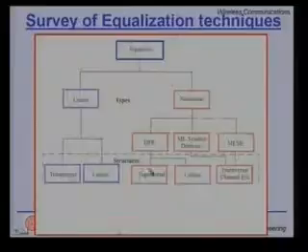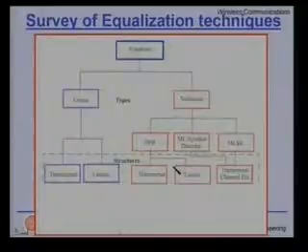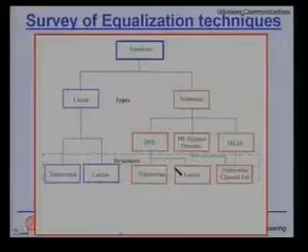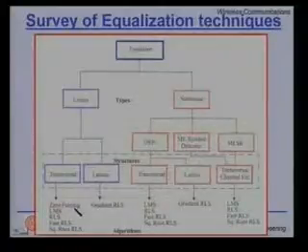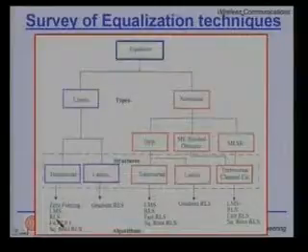Now, for each of these structures, you have the flexibility to use various kinds of algorithms to quickly update the weights. Most of them are recursive algorithms. You could either use the zero forcing or LMS, least mean square, or RLS, recursive least square, or the variations thereof.